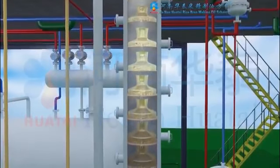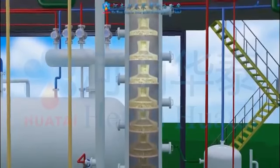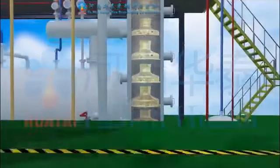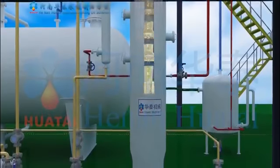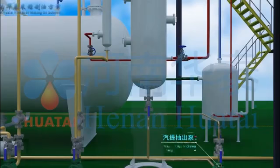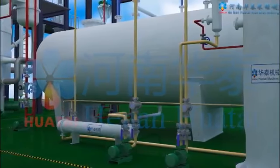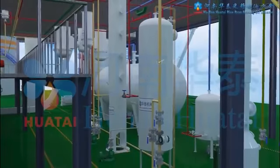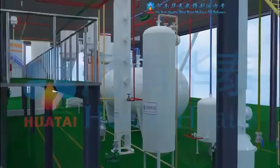Through a disc shunt inside the steam stripping tower, the mixed oil forms thin films on the stainless steel discs, and the extracted crude oil is further concentrated to achieve the state standard. The extracted crude oil from the steam stripping tower is conveyed to the oil heat exchanger by the steam stripping extraction pump. After the heat exchange, it is sent to the crude oil temporary storage tank.